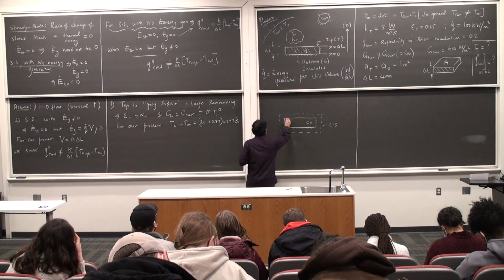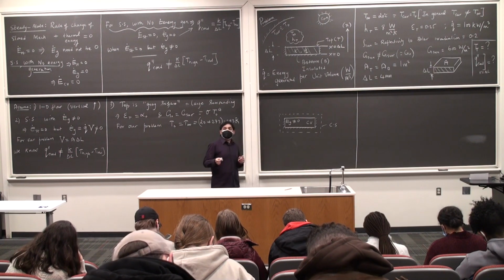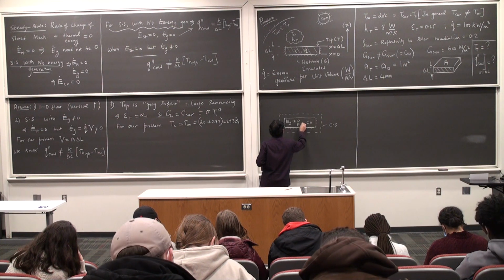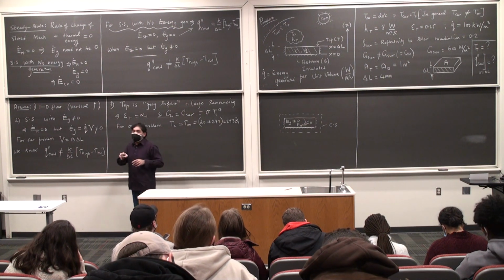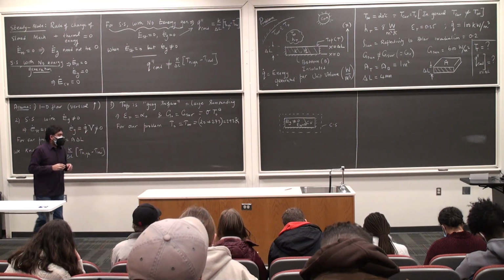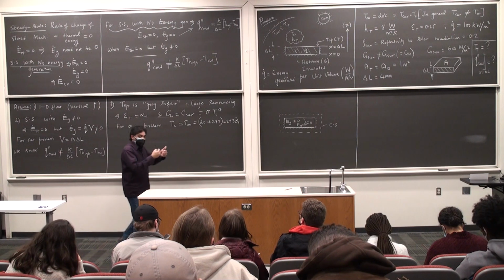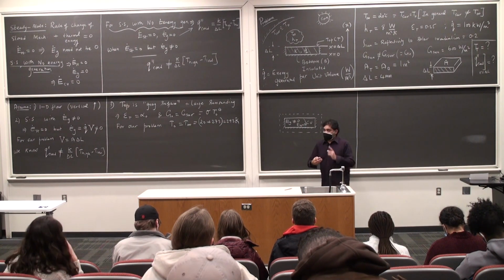So I'm going to have E dot G is not 0, E dot stored is 0 because I'm at steady state. Okay, so this is within the control volume. These are volumetric phenomena. Then we start listing one by one all of the fluxes that are occurring in the problem.